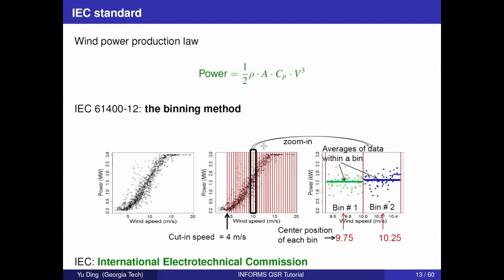For example, you have an airplane taking off, right? The wind is coming here, so the relative angle between these two is the attack angle, and the wind speed plays a role. In wind turbine control, they have the yaw control. The pitch control doesn't really affect the wind direction much. The yaw control really helps the wind turbine point to where the wind comes from. But the yaw control cannot be exercised too fast, because the wind turbine nacelle is very heavy, so they can only change the direction slowly. Therefore, when the wind actually changes suddenly, there's always some sluggishness.